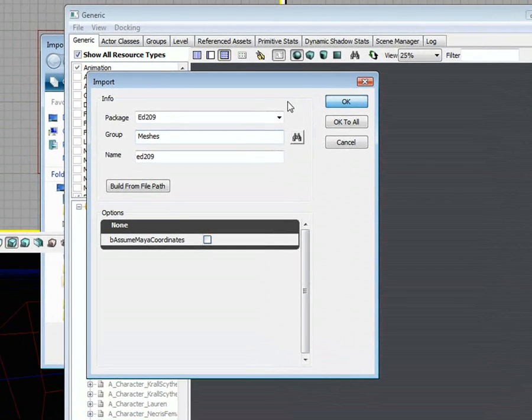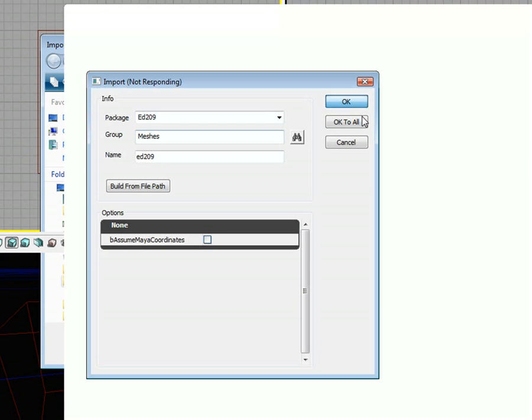Now, a word of caution for Unreal meshes. I advise you guys, if you're going to work with actually creating vehicles, characters and other bits and pieces, to look at other tutorials to find out coordinate systems. Max will sometimes have some issues with exporting to Unreal 3, and you will need to make sure that you rotate your model in the correct direction. I'll show you how to fix some of these things when we come to actually importing this mesh into the level.